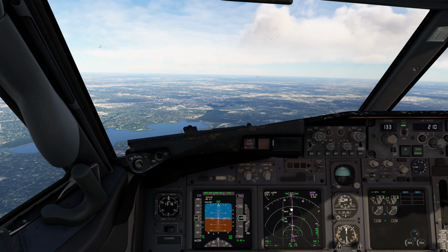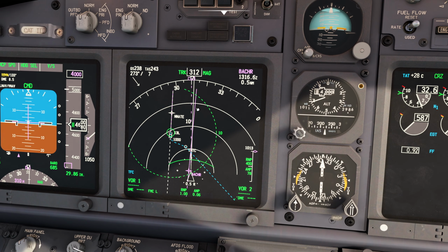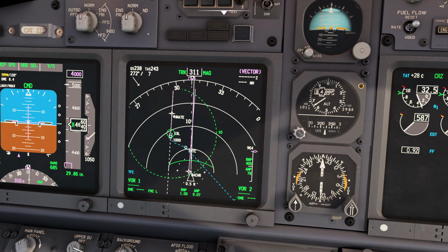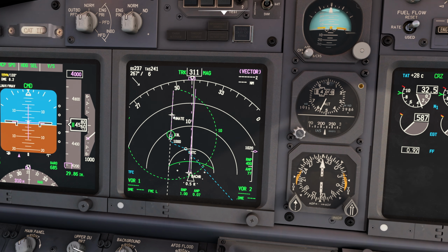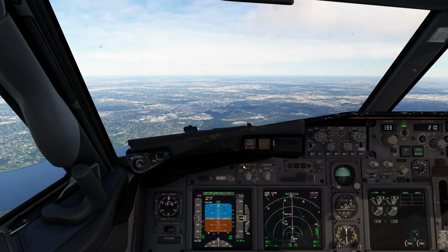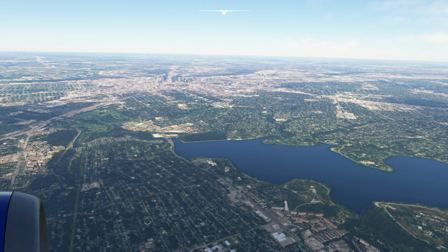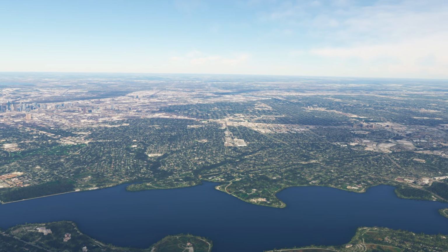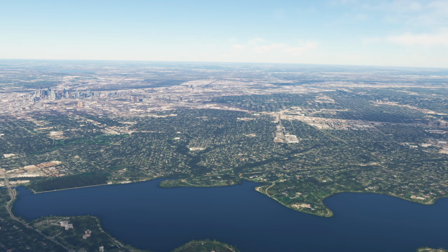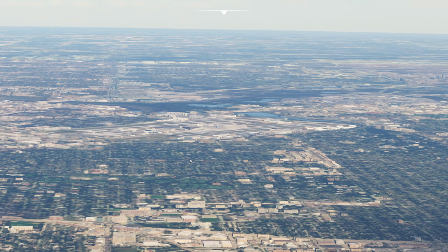And if you look at the screen here, here's our location flying this direction. Here's the runway right here, and then here's that first localizer waypoint. This is where we capture the localizer. So you can see he's basically flying us a left downwind. We're flying downwind to the airport right now. If we look out off of the left side of the aircraft, we're going to see the airport. There's downtown, and the airport should be right over here somewhere. There it is, right there. There it is.